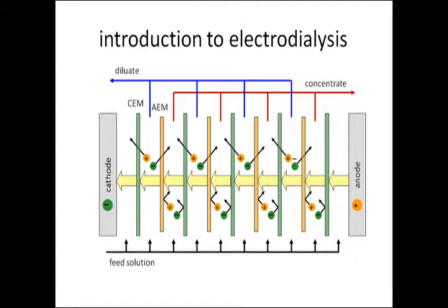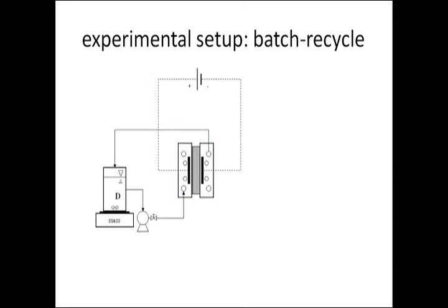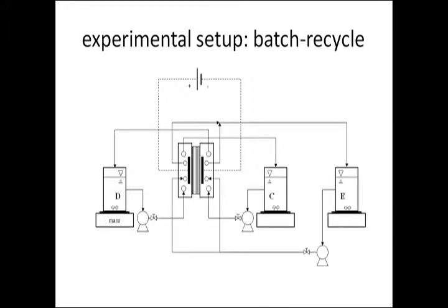So there's a current that runs through there, and so Shane Walker, who was mentioned earlier, who was a PhD student of mine who did this work and is now a professor at UTEP and is in the room somewhere, developed this system. At the center here we have this small electrodialysis system, and a diluate reservoir and a concentrate reservoir, and you need to use an electrode rinse because there's gases formed at both the electrodes that you have to get rid of. And in a real system you may have 100 of these pairs or 200 pairs. In our system we had just 10.